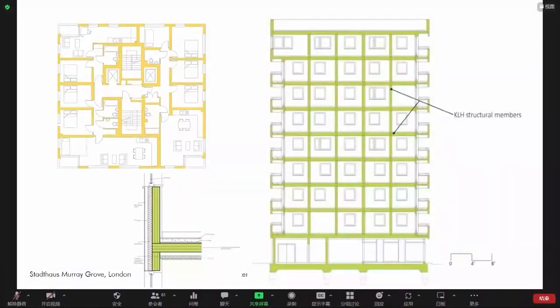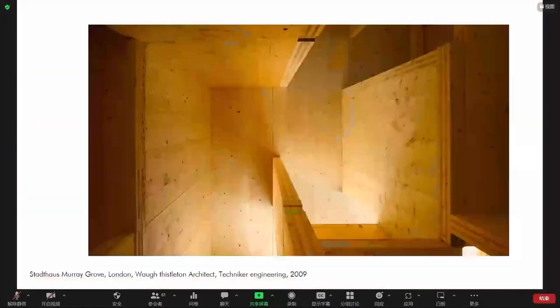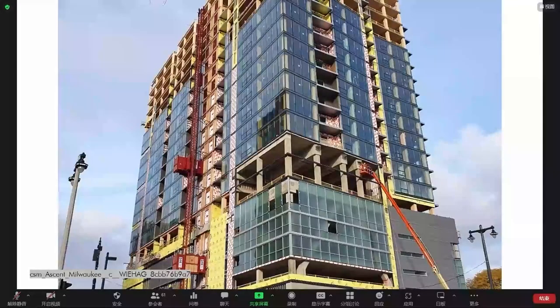Just to show you what has been developed, there was a specific jigsaw connection between the walls and the ground, giving this appearance as a structure, and you see the connection system that was developed. But at the end, you cannot see any timber in this building, which has been protected by plasterboard for the fire dimension. You have also other approaches that can be followed for designing high-rise timber.